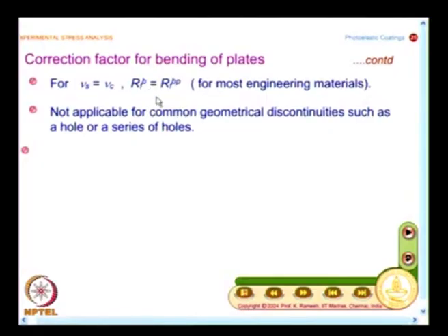These are all the developments in the old days where they had only slide rule to work with. Now you have computer software available, you have to just put in your thickness of the specimen and thickness of the coating and material properties. You can even select it from a database, you instantly get the correction factors. Even if it is not available, you can write your own code. So the days are different now, though the expressions look very long and unwieldy. It is necessary even to do simple calculations in reflection photoelasticity, you cannot ignore it.